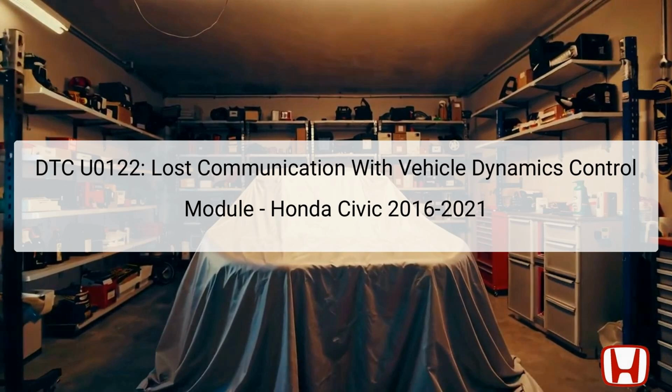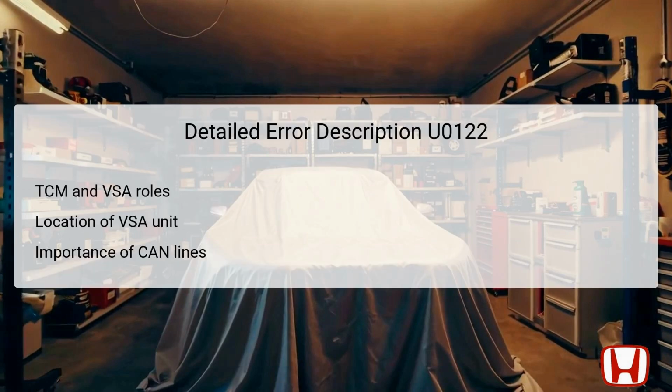This may result in functional limitations of the vehicle's electronic systems, affecting performance and safety. Understanding the components involved is crucial for effectively diagnosing the issue. The Transmission Control Module, TCM, oversees the vehicle's transmission operations. The VSA Modulator Control Unit is responsible for managing stability and traction control by processing signals from several vehicle sensors. It is typically located near the brake master cylinder or in the engine compartment.